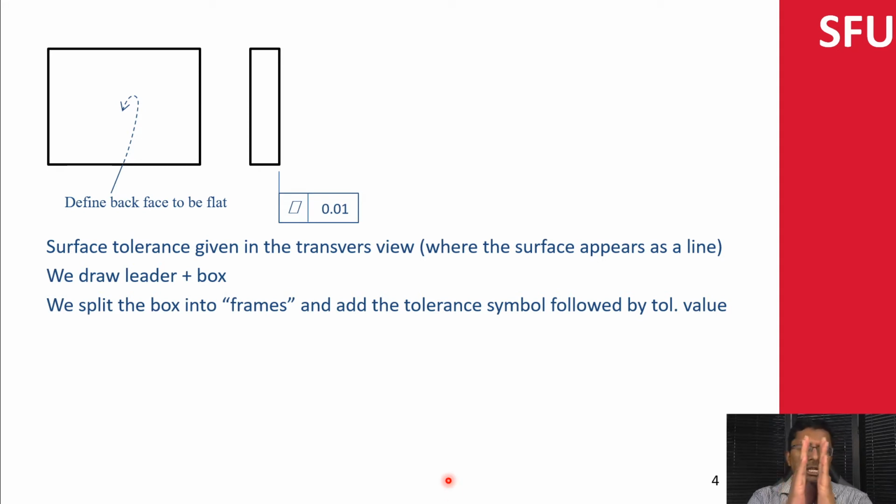So you have these two theoretical surfaces, right? It doesn't matter which one you pick. These are going to be a reference datum. Typically what will happen is you will say, I want the bottom surface to be flat, and then you lay it on the bottom. And so that bottom reference becomes the datum that you can use.